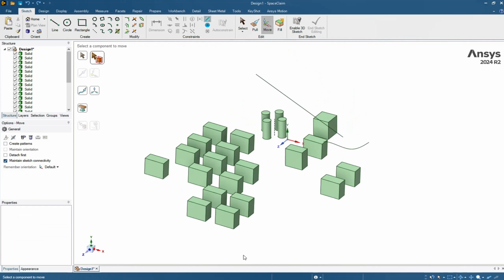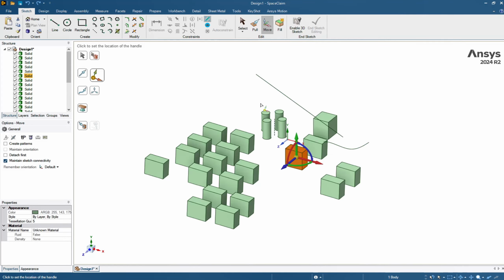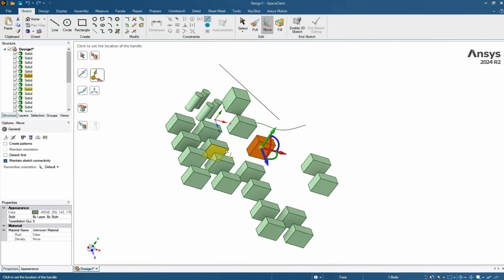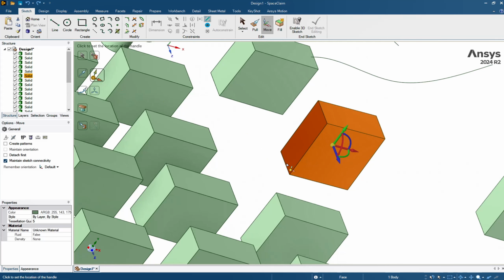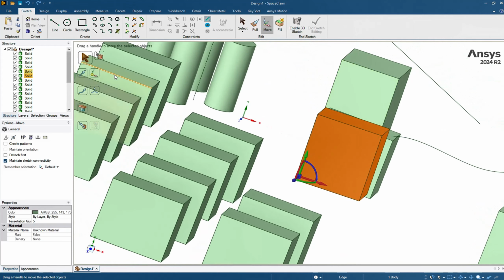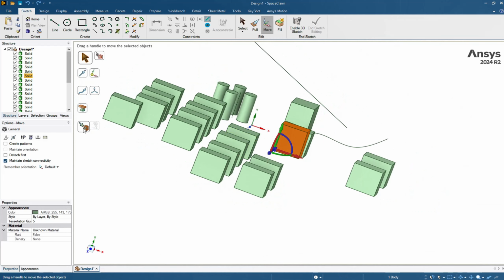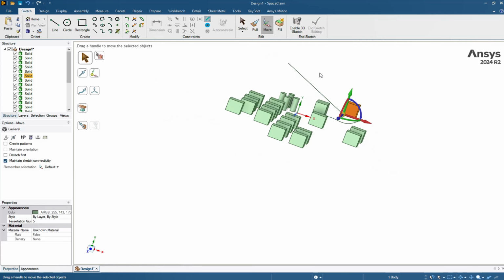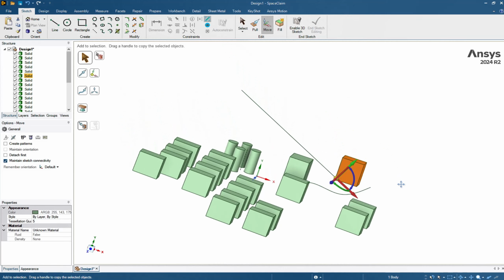Now, similar to the previous examples I explained, I align the movement direction of the cube exactly along the drawn diagonal line. First, I use the Anchor command to place the reference point on the bottom edge of the cube. Then, using the Up to option, I move the cube to the starting point of the diagonal line and place it there. At this stage, by activating the Move Directional option, you can see that our object moves precisely along the diagonal line and fully aligned with it, exactly in the way we want.